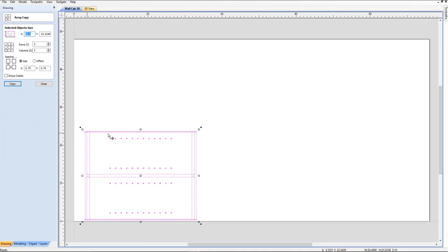Now what I want to do is, I think we've got a 30-inch cabinet. We have a 96-inch piece of plywood that we should be able to get 3 out of. We had a 24-inch width on our desktop max, and with 48, we should be able to get two rows and 3 columns. So I'm going to select that here: 2 rows, 3 columns, and we're going to put a gap.